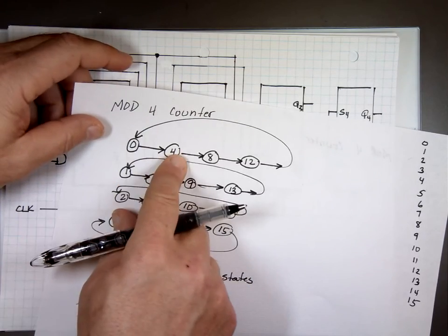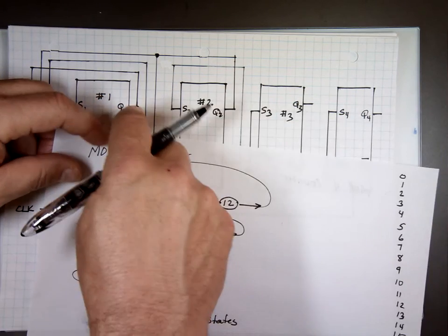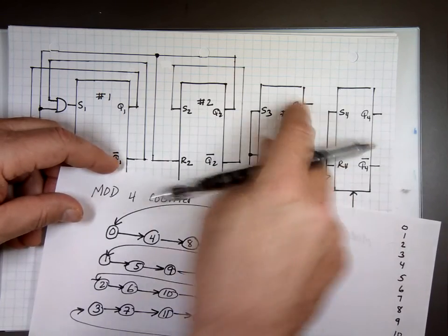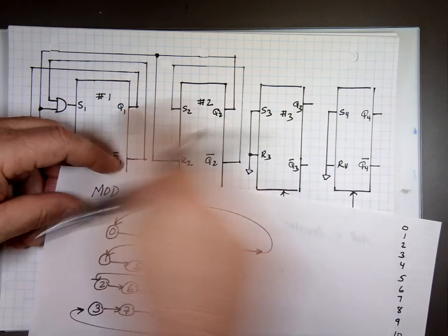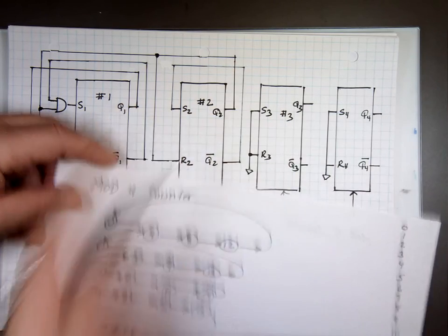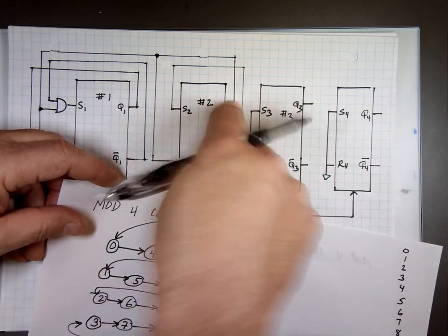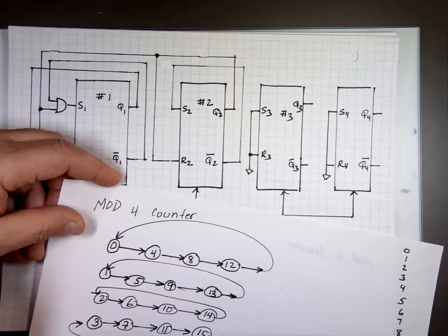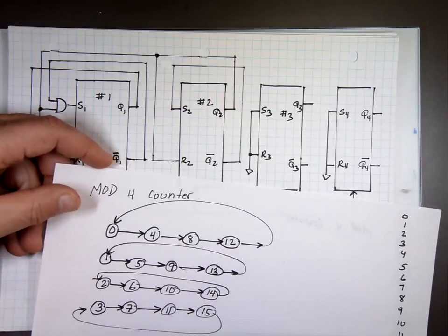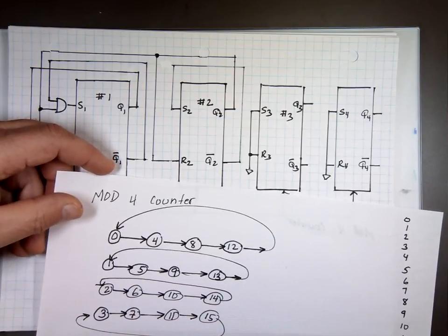So you'll see off, off, on, off. Then the next one you see 8. Off, off, off, on. So off, off, on, off, that's 4. Off, off, off, on, that's 8. The clock comes in, 12. So it works as binary. And Q1 is the highest one, so 15. The way I drew them, that's the one on the left.